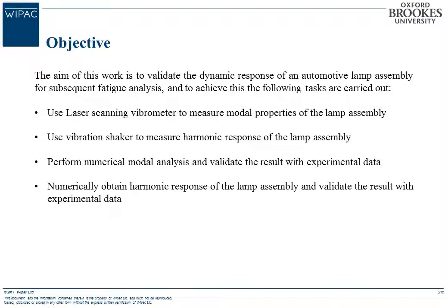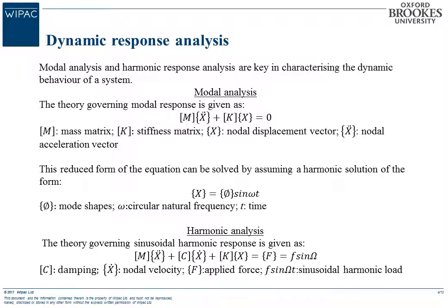Perform numerical modal analysis and validate the result with experimental data. Numerically obtain harmonic response of the lamp assembly and validate the result with the experimental data. Dynamic response analysis: modal analysis and harmonic response analysis are key in characterizing the dynamic behavior of a system.